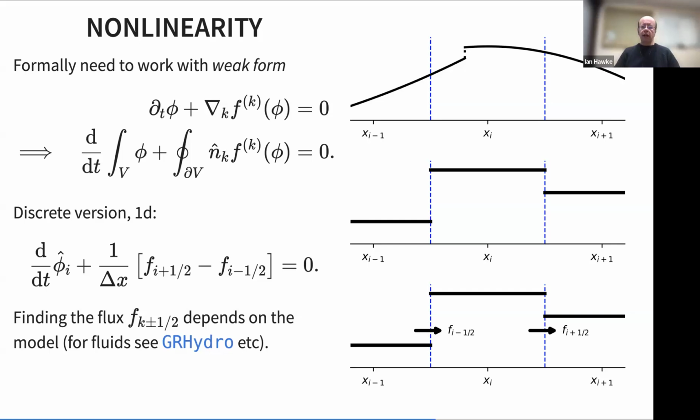So particularly in the evolution of matter, where we have balance laws of this particular form, what we get is the formation of shocks, discontinuities, from smooth data. So at a discontinuity, this derivative just does not make sense. So what we have to do is to basically integrate this over a spatial cell, over a fluid element, in order to get the weak form.